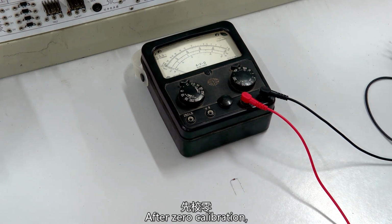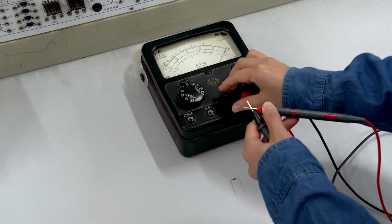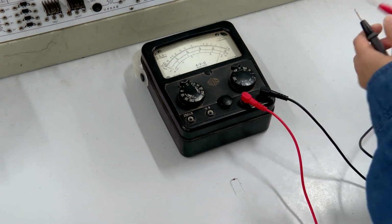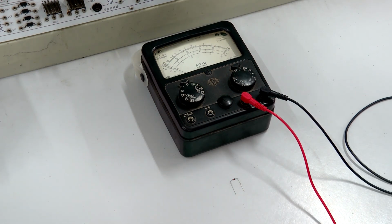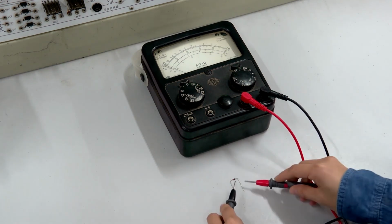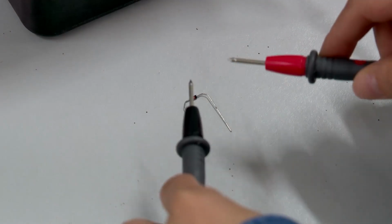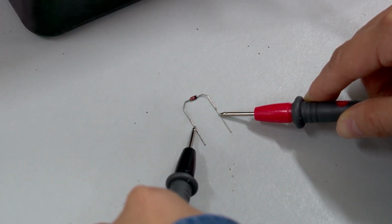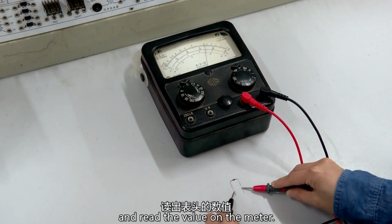After zero calibration, use the two probes to touch the two leads of the diode, and read the value on the meter.